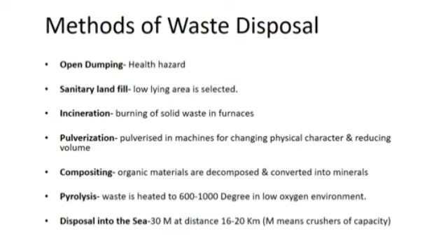Disposal into sea. When we are disposing the waste material to the sea, it should be at a depth of 30 m and a distance of 16 to 20 kilometers. Likewise, it should be disposed when we are disposing into the sea.